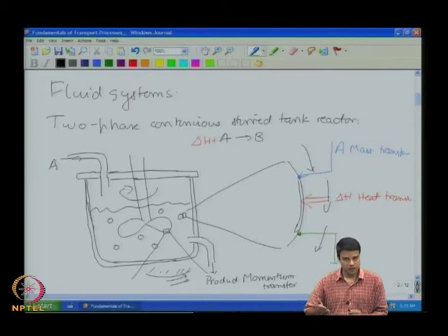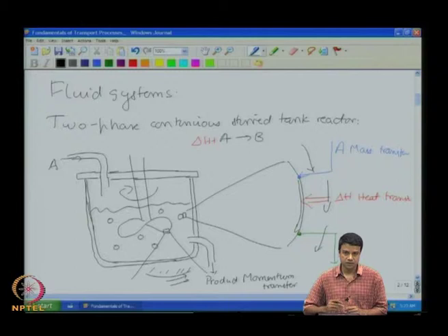It is important that reactant comes in continuously so that the reaction can take place, and it is also important that the product leaves the surface, so that if the product does not leave, there will be no place for further reactant to come in. In addition, the reaction can be either exothermic or endothermic, so you have to supply a requisite amount of heat or remove a requisite amount of heat from the surface. Otherwise, if it is an exothermic reaction and you do not remove heat, there are going to be hot spots that are formed and you could get runaway reactions. If it is endothermic, then if heat is absorbed, the catalyst surface will cool down and the reaction would not proceed at the desired rate.